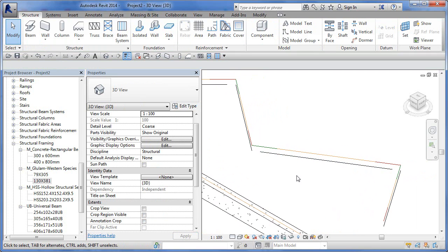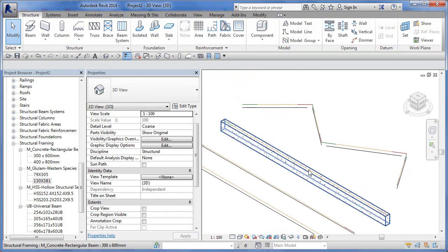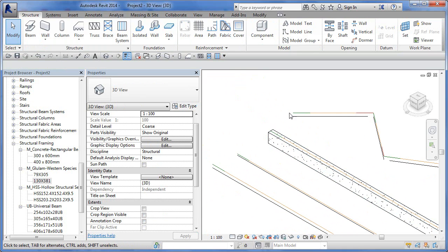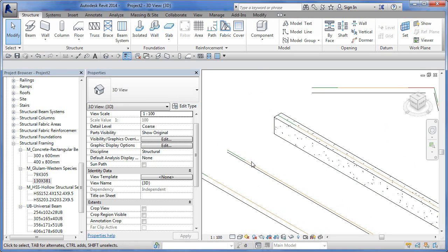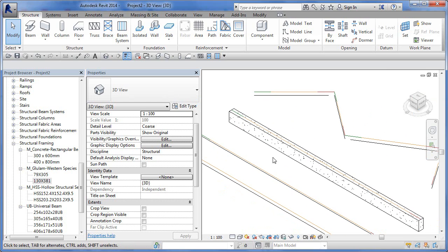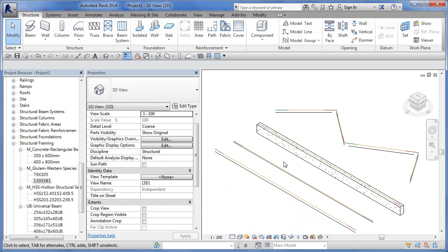Okay, the stick frame is the stick frame. The analytical model is the analytical structural connecting, where all the endpoints have to really join with each other. You can see the analytical model of this concrete beam is at the top, and the same as with these guys. Okay, and concrete doesn't have a stick frame model, so it just doesn't have it.